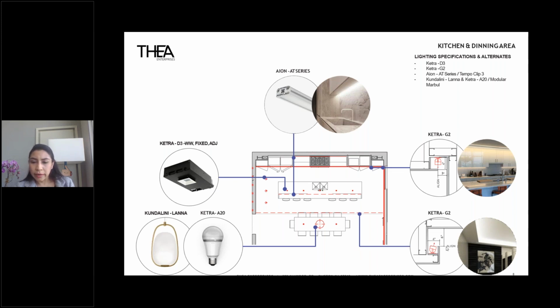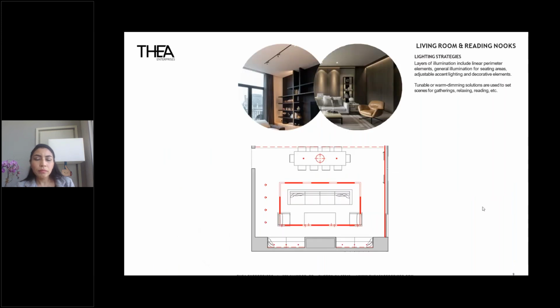And as you can see here, we're again aligning the lip of that cove with the top of the fixture. And we have provided a wide beam optic to really push light as far out as possible. And the intent of aligning this here is so if you're standing far away from the room, you don't have direct view of the fixture, but you are also not casting any shadows in the ceiling.